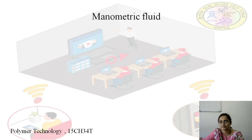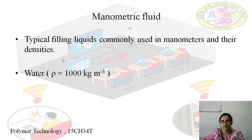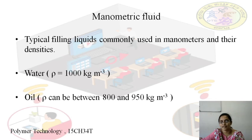Manometric fluid is the fluid which is used inside the manometer. Typical filling liquids commonly used for manometers and their densities are: water, with a density of 1000 kg per meter cube; oil, whose density can be between 800 and 950 kg per meter cube; and mercury, whose density is around 13,560 kg per meter cube. These are the commonly used manometric fluids.